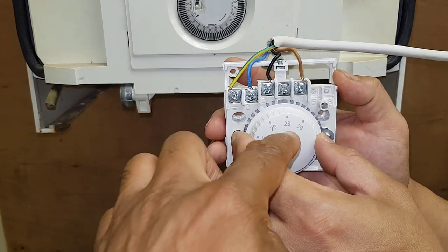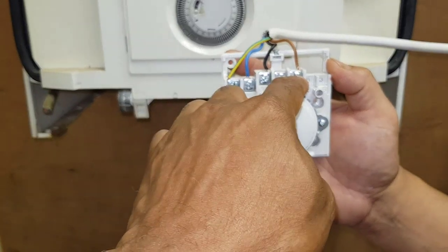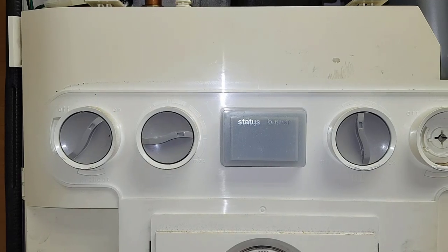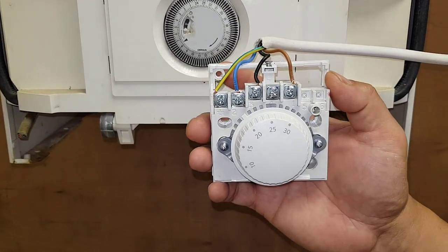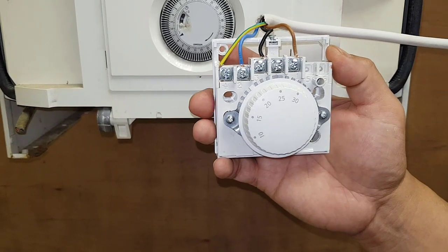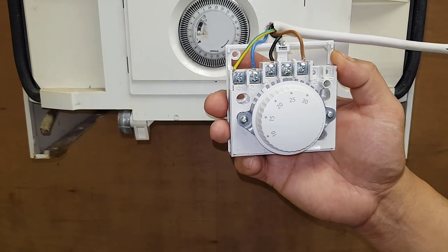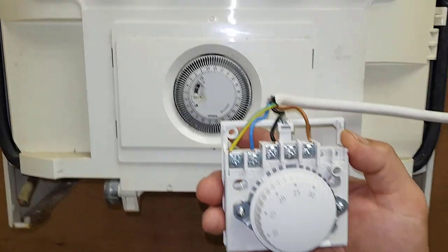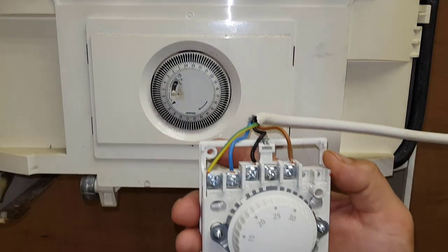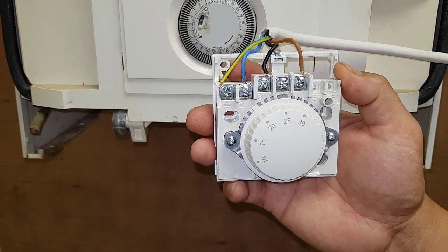Well, you wouldn't need that now, because basically you've linked them together, and then if the C comes on, then you know it's the thermostat. That is the problem. Okay, so that's a bit of fault finding on how you'd rectify it if the C didn't come on after turning the room thermostat on.